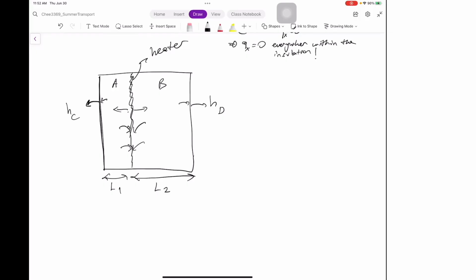And the 4 unknowns would be C1 of the A, C2 of the A, and C1 prime of the B, and C2 prime of the B. And then you can get the temperature profiles for the 2 cases from the 4 boundary conditions, and you can get the fluxes for the 2 cases. So from the C1 and C1 prime, that would give you how the fluxes would be shared in the 2 cases. And you also have another condition, if those boundary conditions are not enough, which tells you that the heater Q is split between Q1 and Q2.